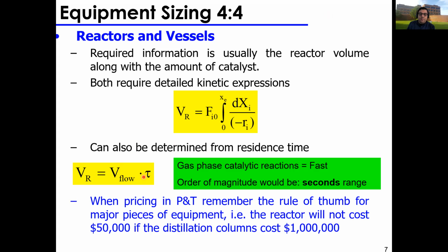And this becomes important in very specific scenarios, especially when you need to control the time a certain species stays in a reactor. For example, a solvent which is expensive, or a species which is explosive, or material which poisons your catalyst, whatever it is. So you only want it to stay in your reactor for a certain amount of time. You can use this as a limiting design metric to design your reactor. And yeah, this is how you design your reactors.